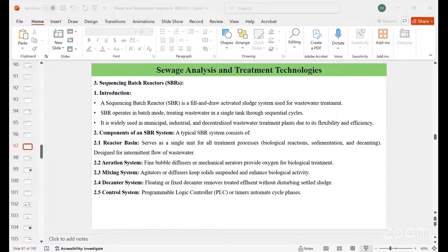So coming to the characteristics of this solid waste relevant to water systems. The main composition of this solid waste determines the potential pollutants. That is, organic waste contributes to oxygen depletion in water, and inorganic waste can persist and accumulate. And leachability, the ability of pollutants to dissolve and be carried by the water, and this is the leachate. Hazardous waste and some industrial waste also have high leachability.